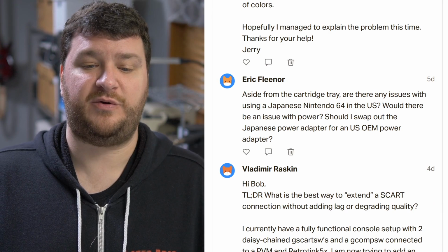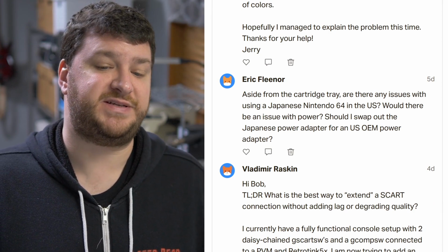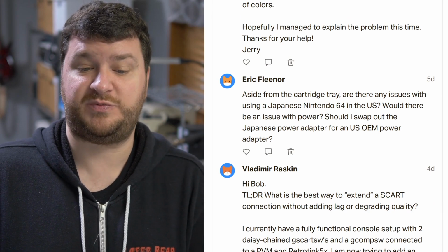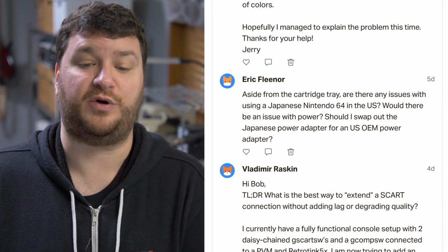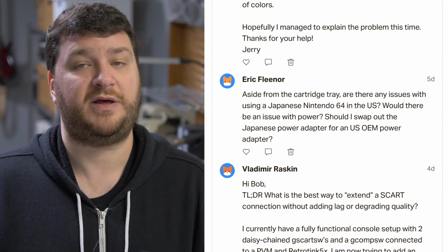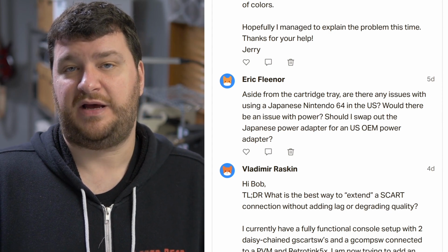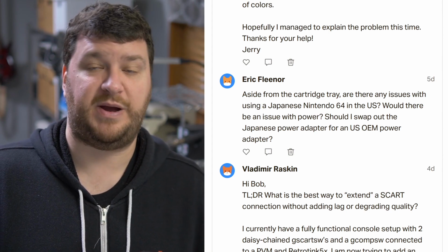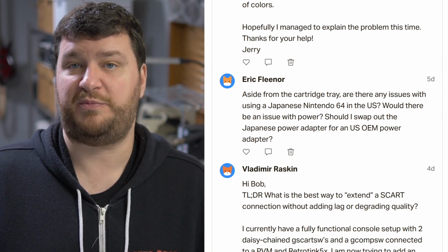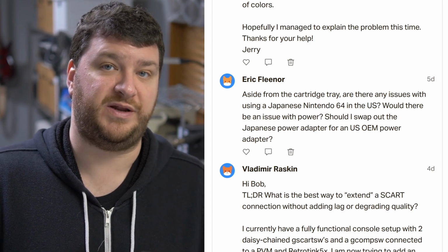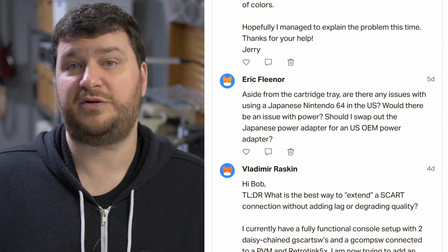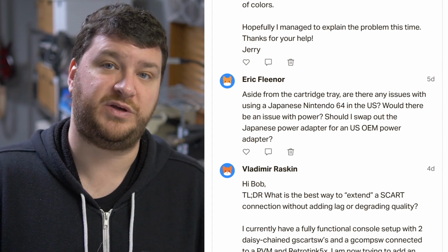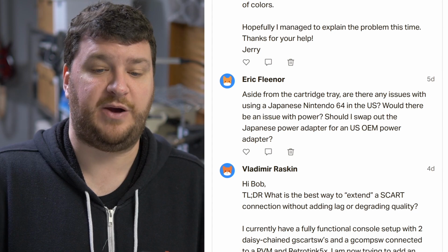Eric Fleener wants to know if there's any issues with using a Japanese Nintendo 64 in the US. Would there be an issue with power, and should they swap the Japanese power adapter out for a US OEM power adapter? So you'd have to start with specs. Are there printed specs that say the input voltage tolerance of that power supply? And if not, and you open up the power supply, is it written on the board inside? Is it variable? Is it something that could handle 100 to 220 volts, or is it really only designed for US or Japan power?